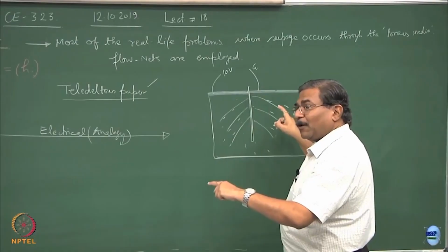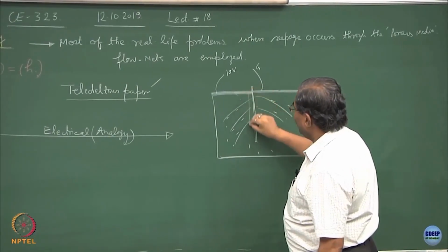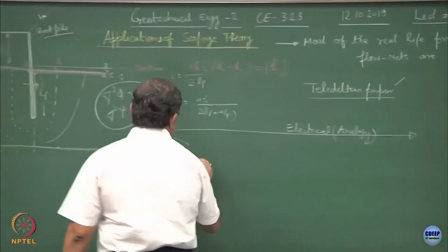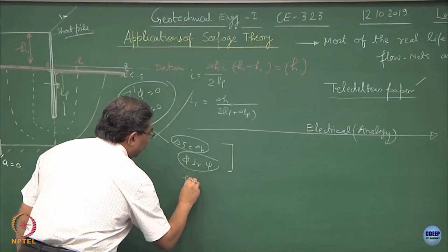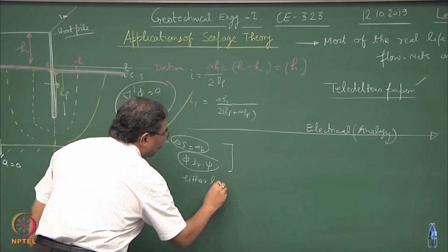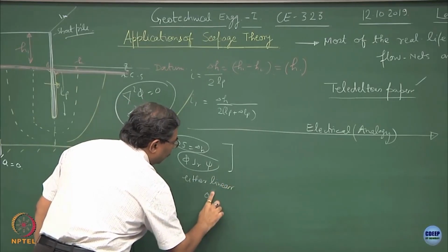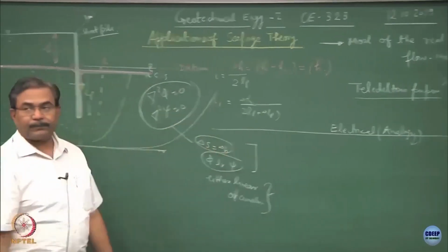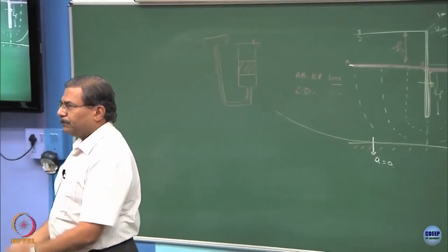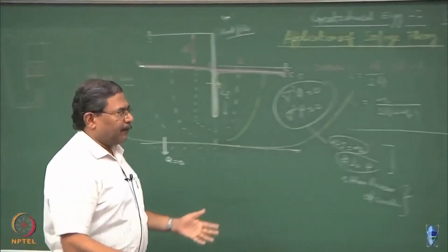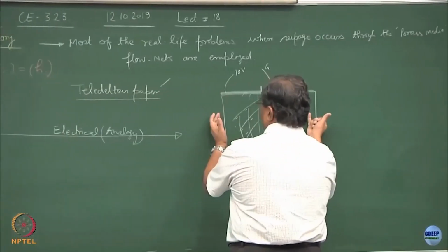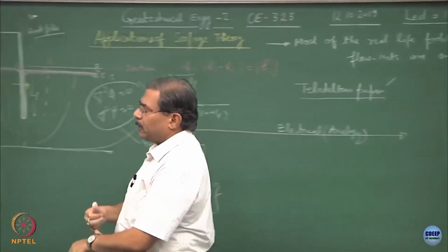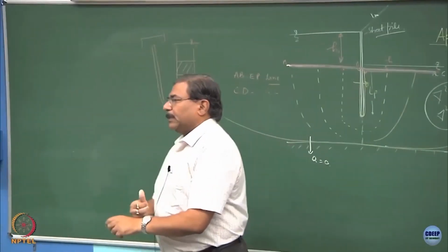Now, once the equipotential lines are obtained, what you have to do is draw the flow lines by keeping these three things intact, either linear or curvilinear, fine. Is this the answer you have understood? Then what should again I be doing? Having done this, I can transform the whole thing on this scale also. Sometimes people use copper sulphate solution also for analyzing these things.